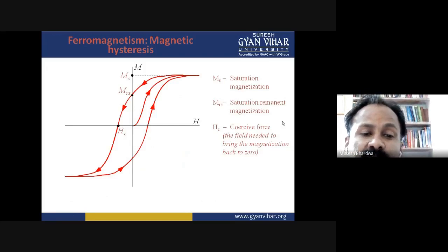These ferrites are composed of barium oxide and iron oxide. Anisotropy produced during manufacturing makes them permanent magnetic materials. Ferrites are magnetized by applying large external fields. Barium ferrites are used as focusing magnets for television tubes and in small DC motors in compact torque drives.